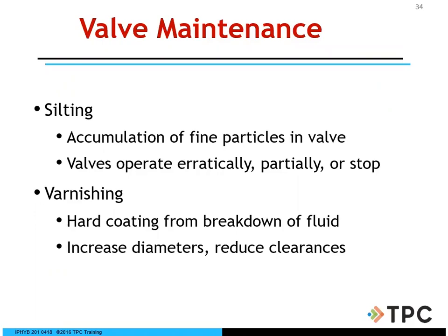So what about valve maintenance? I talked about heat. If your hydraulic fluid is overheating in the system, there will be an accumulation of fine particles in the valve. That's what we call silting. Valves operate erratically, partially, or even stop. They don't work at all.